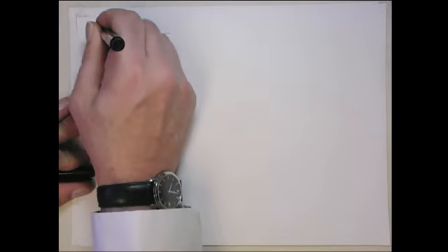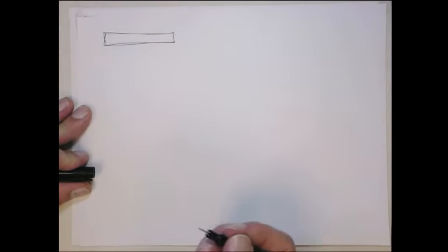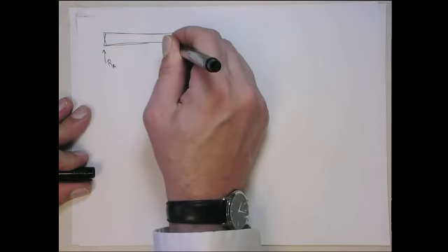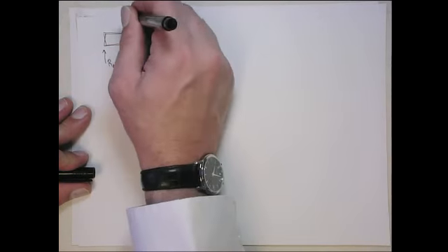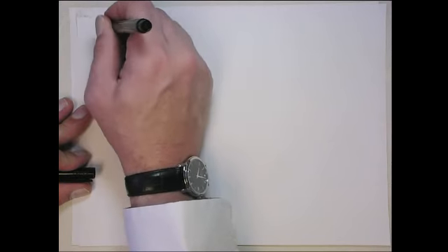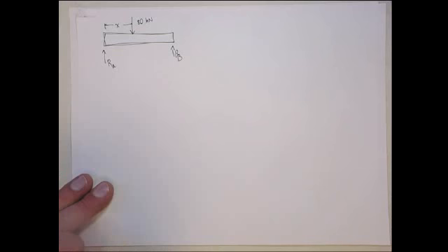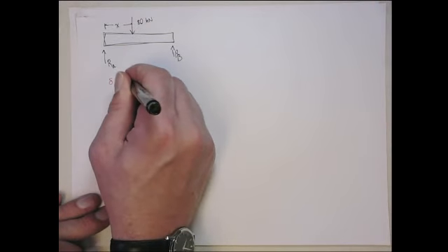Okay? So again, if we draw the picture, here's, oh, that's not so good, but okay, bear with me. That's supposedly the rigid beam. We have a reaction force at A and a reaction force at B, reaction B. And then here's the 80 kilonewton force downward, and it's at a distance X in from point A. All right? And the constraint has to be that the elongation in A has to equal the elongation in B.